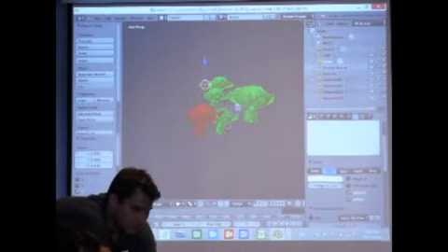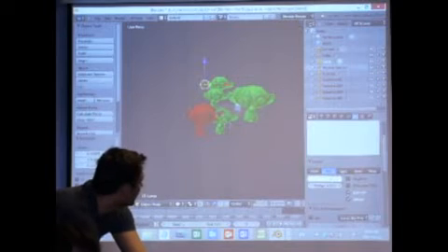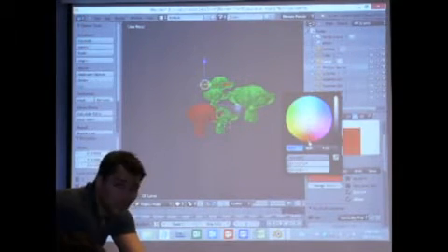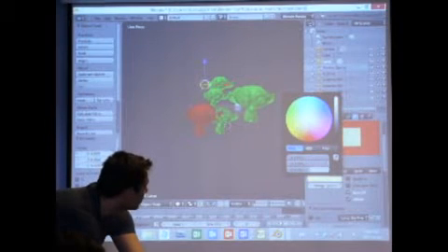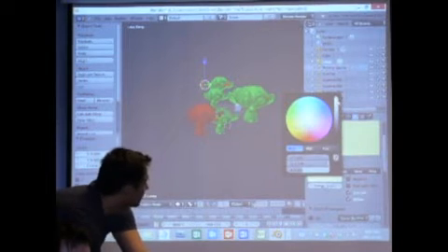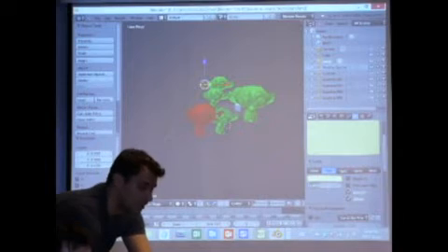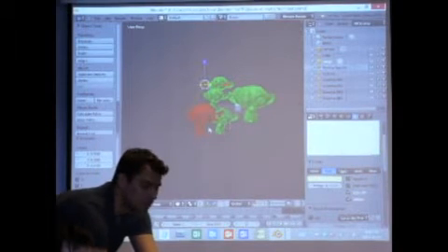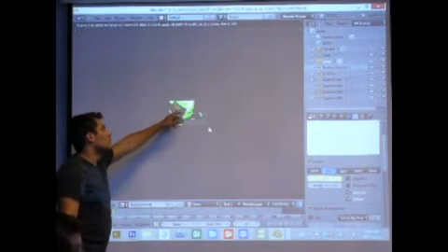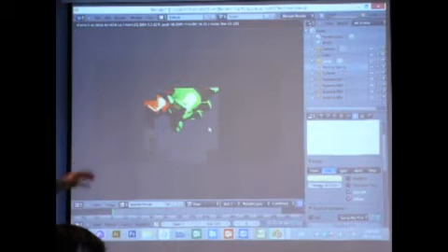And right below this lamp, you can change the color of the actual sun. On the right side, it's white, but you can select this and create a red light, or a yellowish one, or any color you want, and change the actual intensity. Another way to change intensity is to change the energy. If you change the energy to 10, it's going to be incredibly bright, and you'll see really bright reflections around it. You usually want to keep the sun's energy about 1, the way it's set.